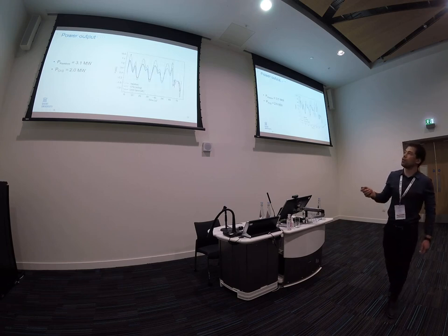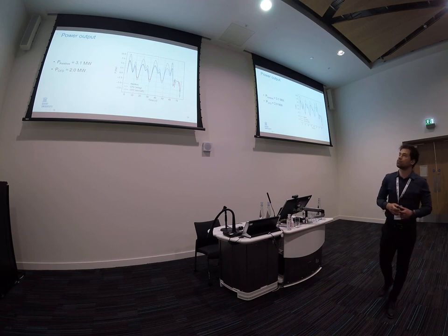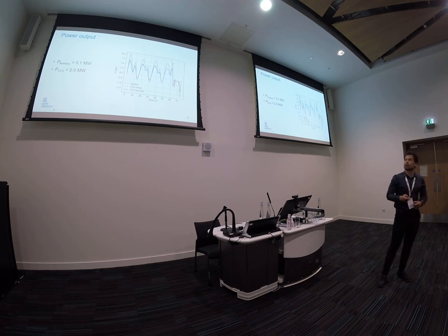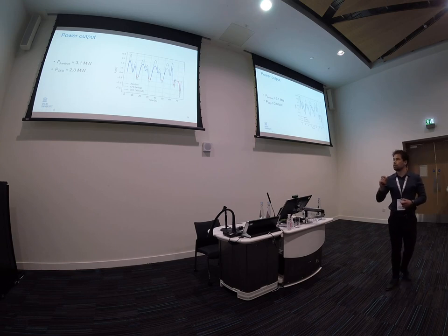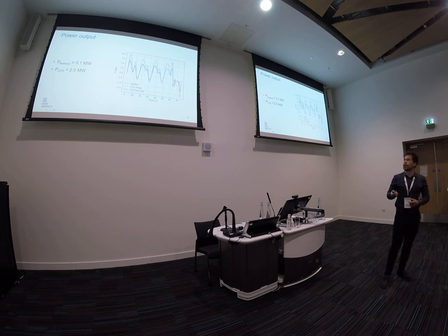So this is what the power profile looks like in time. I plotted here the power prediction of AWEbox in the dashed black line, and then in the dashed blue line we have a power prediction using the aerodynamic forces of the CFD model. The dashed line is only the wing, and the solid line is the complete aircraft. You see between the wing and the aircraft there's not much difference, but less power with the full aircraft due to the extra drag. But there is some difference between the AWEbox prediction and